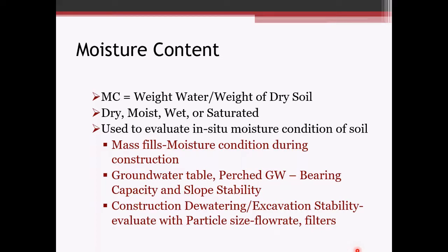So to get into the moisture content, geotechnically speaking, excessive water is not a friend to soil. As the water content increases over the optimum moisture content, then the shear strength typically decreases and the compressibility typically increases, particularly for fine-grained soils. It's a very simple, very common test, and the general descriptions are dry, moist, wet, and saturated, whereas moist is typically where the material is at its optimal moisture content for compaction.